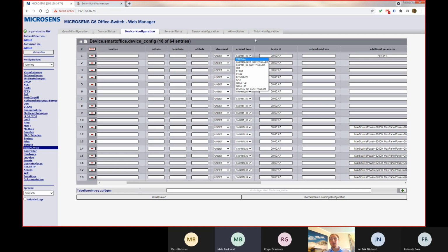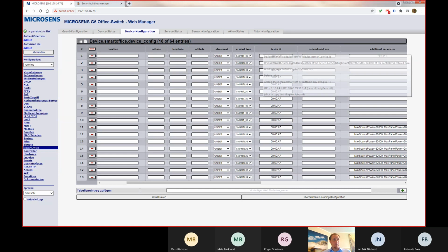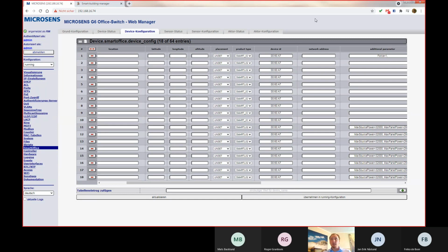Interesting. The benefit is mostly you don't need batteries. The energy for the telegram is created when you press the button. It's just a little bit louder, the click, but this is enough energy to create the information and send it out in the area of a room. We have 30 meters in total, but let's be clear, when engineers say 30 meters, in reality it means 10. But this is sufficient for room automation, and we did a whole building with it.